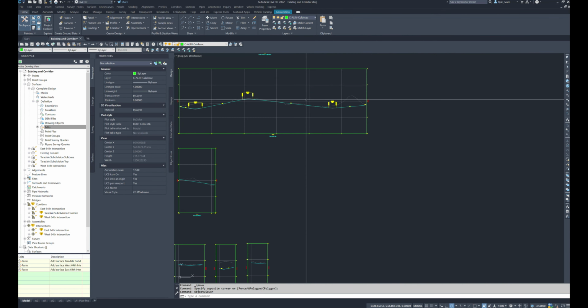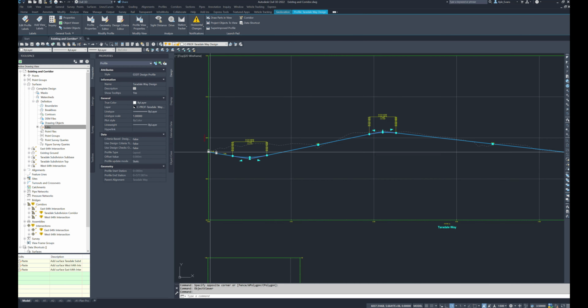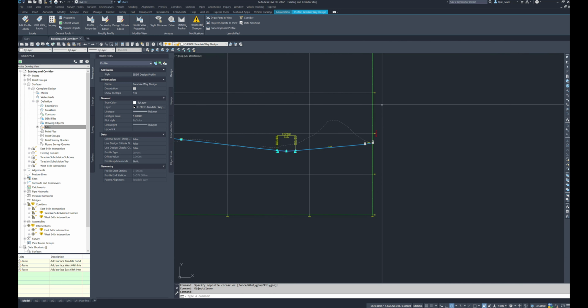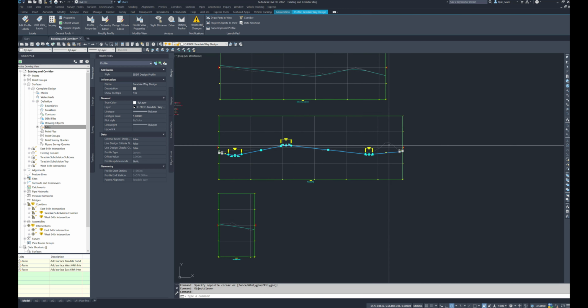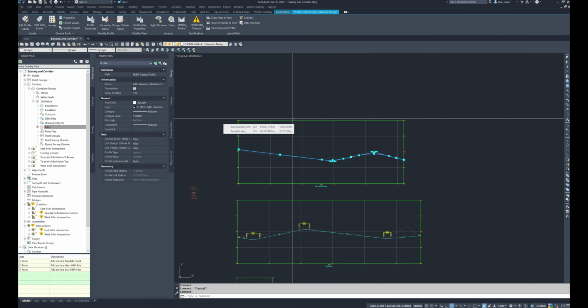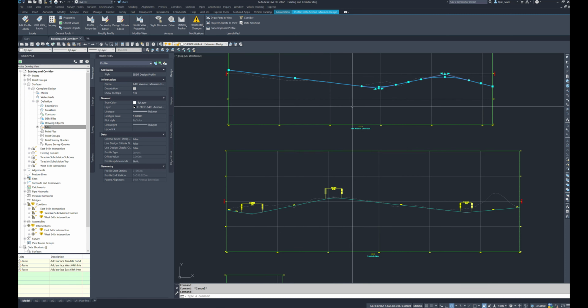Now, if we take a look at the profile views, and we take a look at this one here, we will see that we're now constrained on the left side and we are now constrained on the right side. We cannot change those slopes of the road where the locks are. And again, leave them locked together. Don't go modifying them. None of this has been locked because this profile, the elevation is being controlled by roughly in here and roughly over here somewhere. So where they're tied together, it's the 64th Avenue extension that is guaranteeing where these are located.